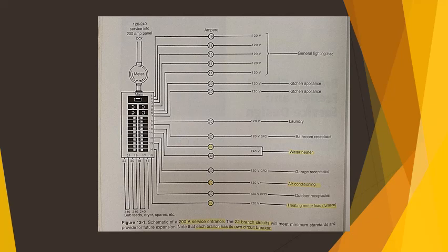The total of all branch circuit loads can be calculated after you know the square footage of the living space, the number and size of any large appliances, and the largest size of any non-coincident loads. The following sections will explain how you can use this information and the rules of the NEC to quickly calculate various types of loads that may be found on a branch circuit.